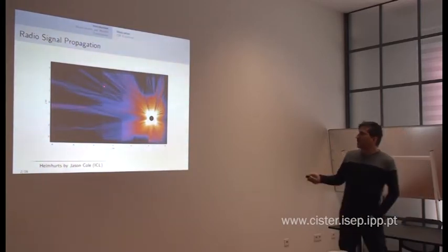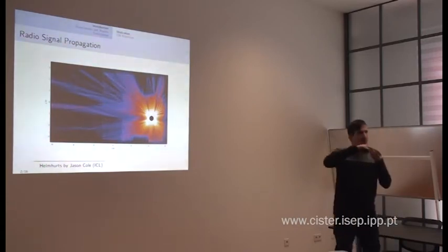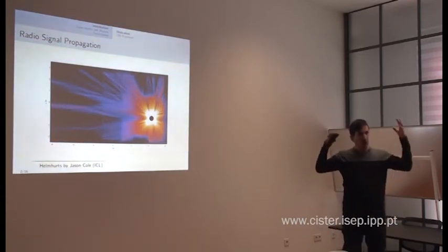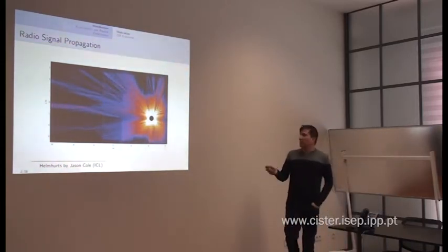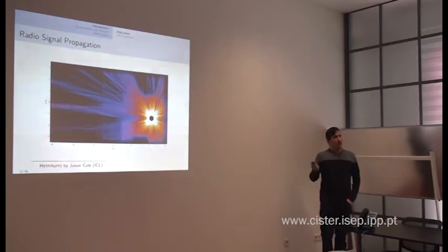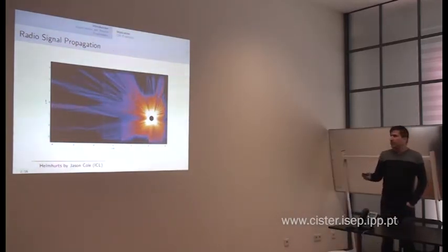On the contrary, in an indoor environment like here, there is reflection of this wave off the roof, the walls, and so forth, and what we get is something like this. That is bad news if you want to use a wave propagating like that to carry information, because you may happen to be in areas where the signal intensity is very weak.